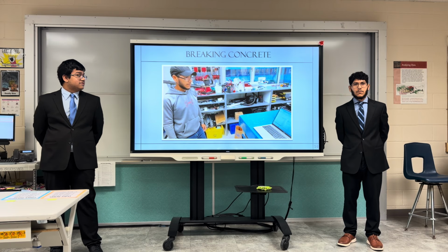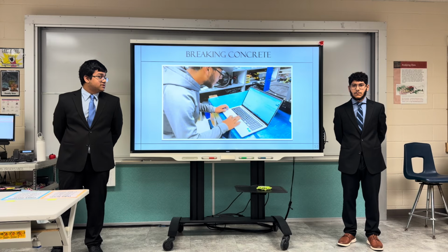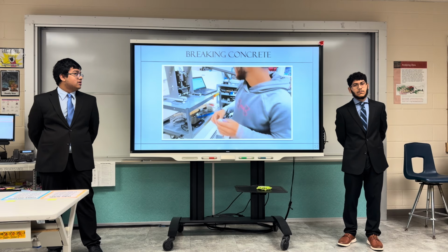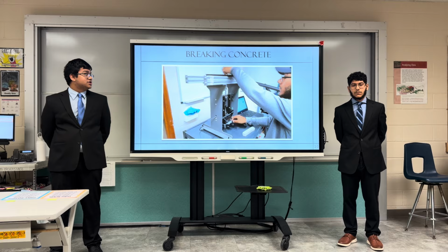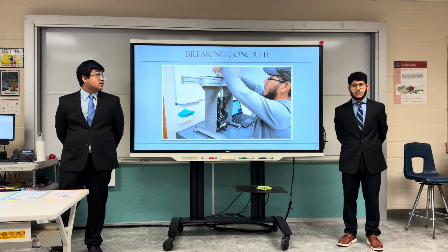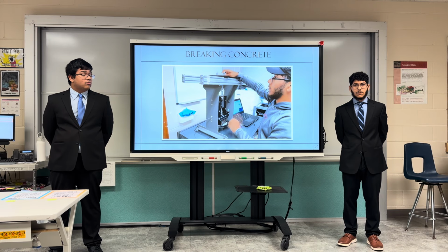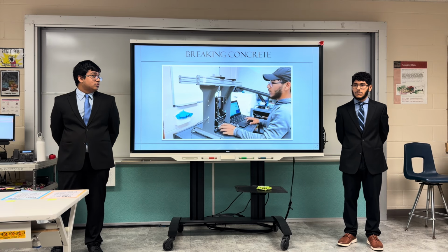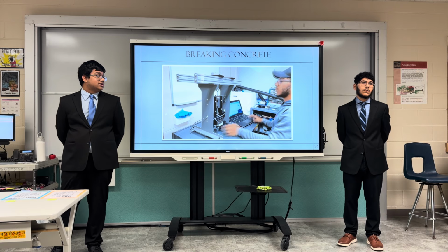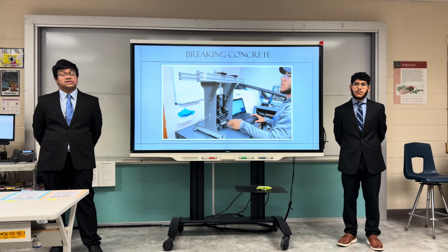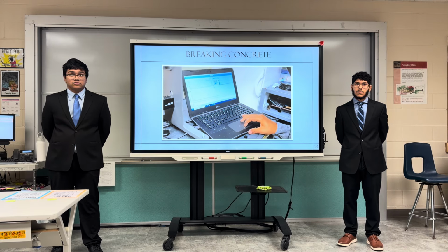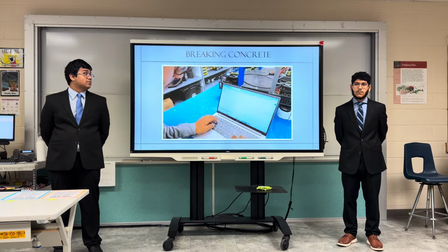Next, we'll go over our procedure for actually breaking concrete. First thing we do is select an appropriate beam, cured or uncured, for putting it into the machine, making sure it's centered and tight. Then we slowly apply more and more force until the concrete beam eventually breaks. After that, we measure the maximum force withstood on the laptop and then put it into our Excel sheet where the formula for converting force withstood to flexural strength is applied.